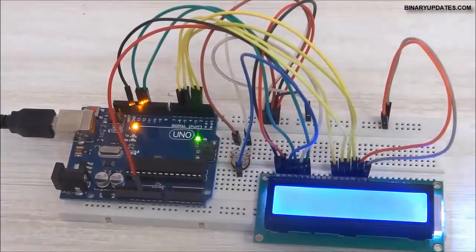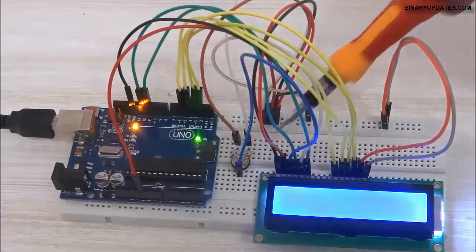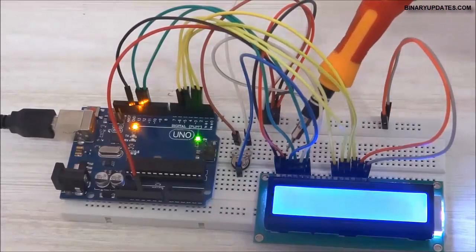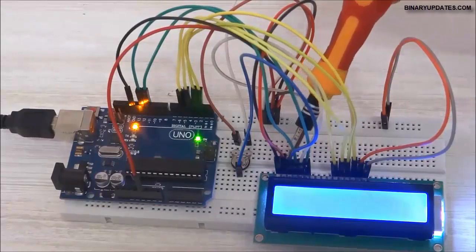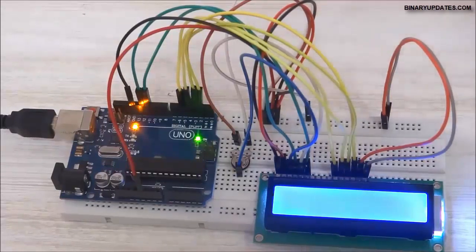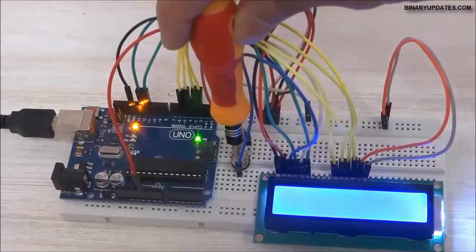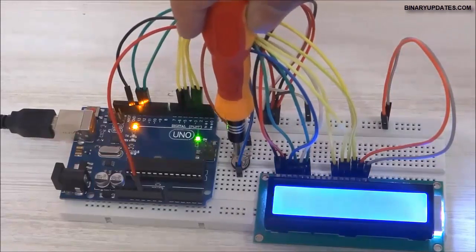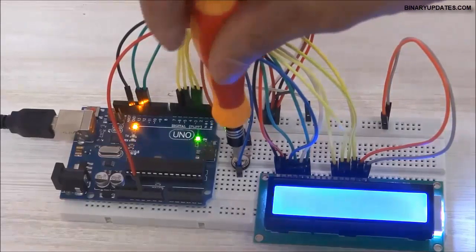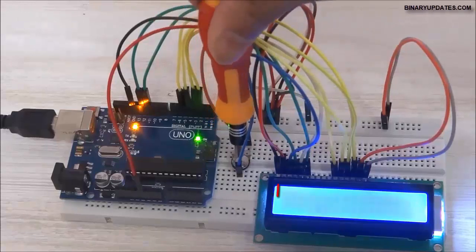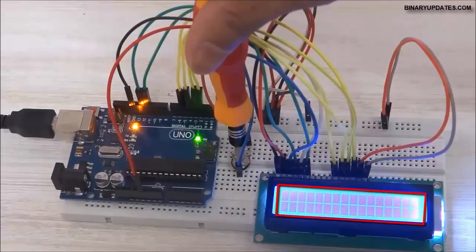The second thing to make sure when you test your LCD out of the box is to check whether you can change the brightness of the LCD or not. This is the basic function, and as you can see, there is a 10 kilo ohm potentiometer that I have connected to the V0 pin, which is, I think, the third pin, hopefully. And as you can see, there is no pixel, there are no boxes on the LCD. As soon as I reduce the resistance, as I move the potentiometer around, you can see the boxes coming up, and as you can see now the boxes have come on the LCD.